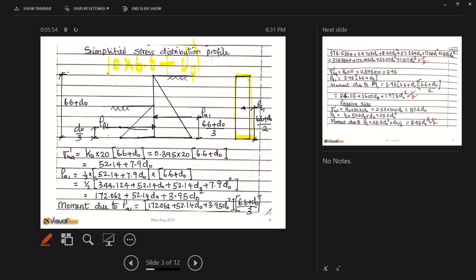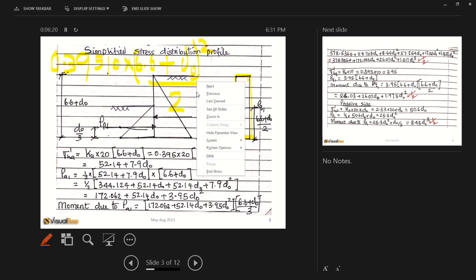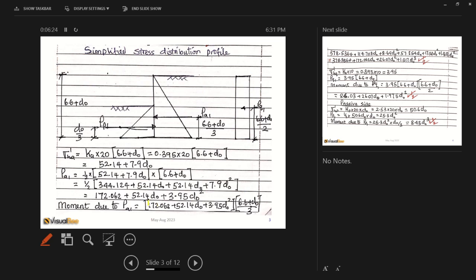That's the area, but don't forget to multiply by the coefficient of lateral earth pressure, which is 0.95. That would be the force, and times the distance to the center, which is 6.6 over 2, so that becomes squared, and this is divided by 2. So that's the moment. Now you have an expression for the moment.